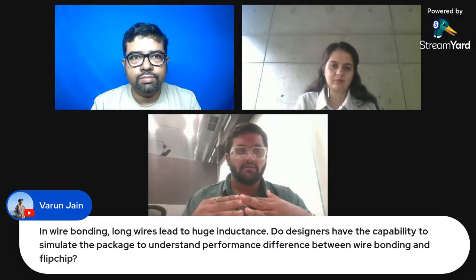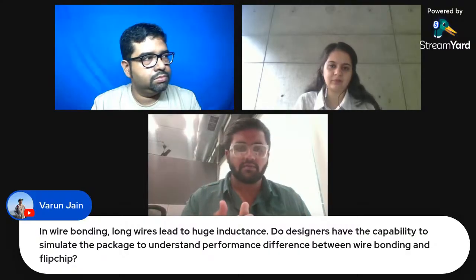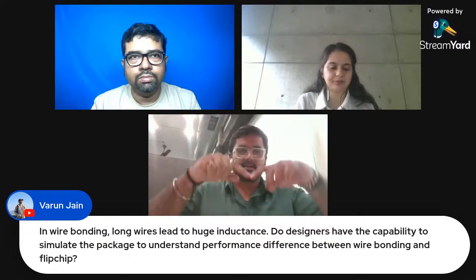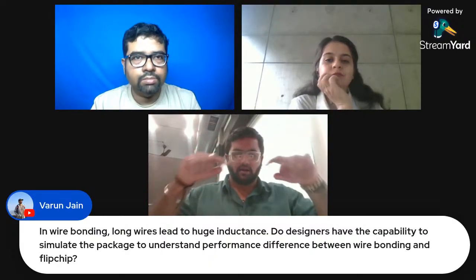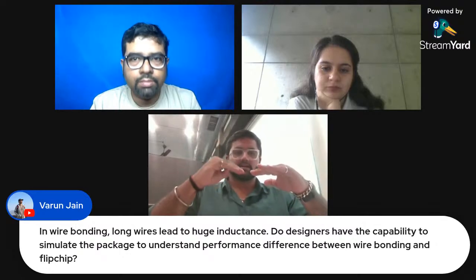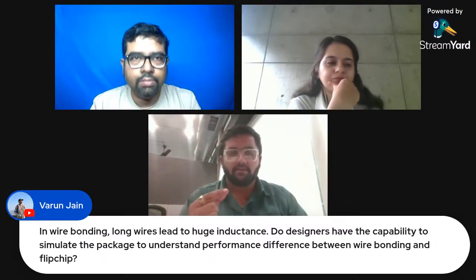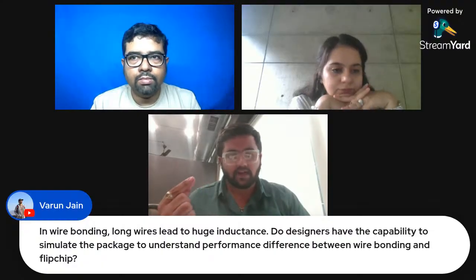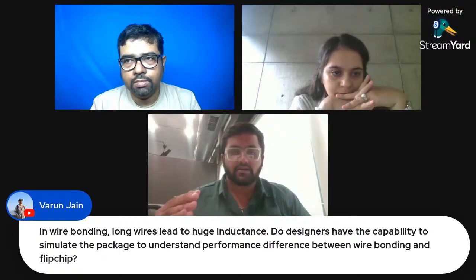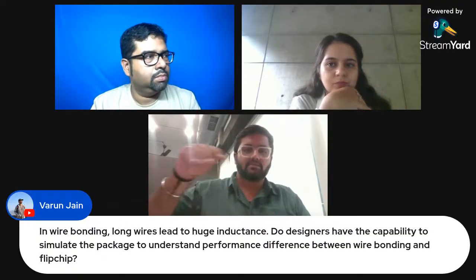It is the best way to understand how to remove a huge inductance. I take a big IC in the middle, and then connect it through other bond pads. And even for the stacking, I'll stack small ones one by one, and then bond them. So even though the bonds and wires are very small, the inductance will be less compared to the huge wire bonding stacking.